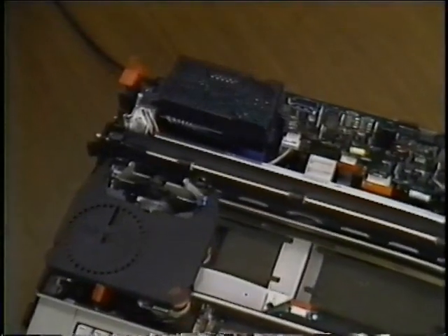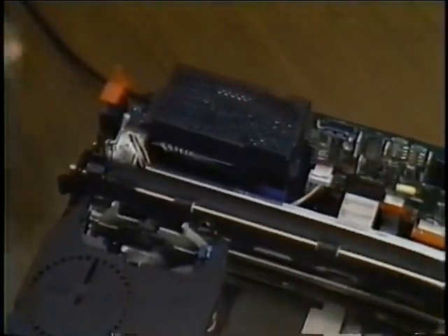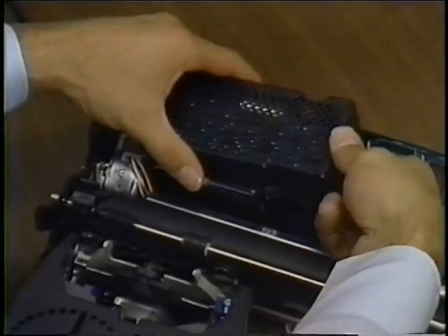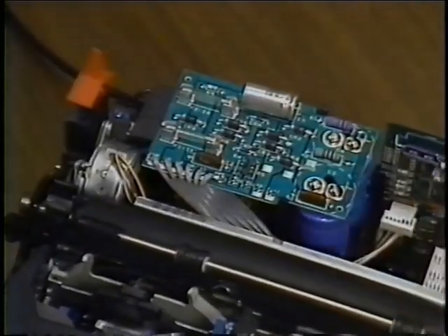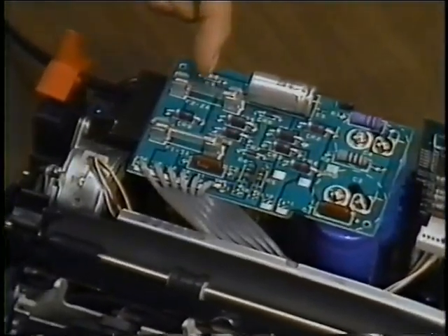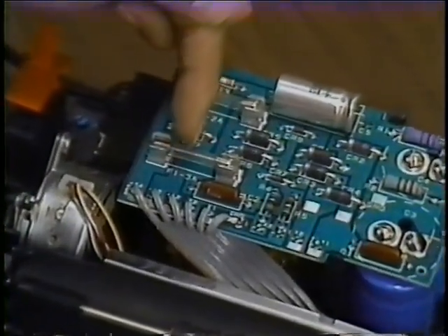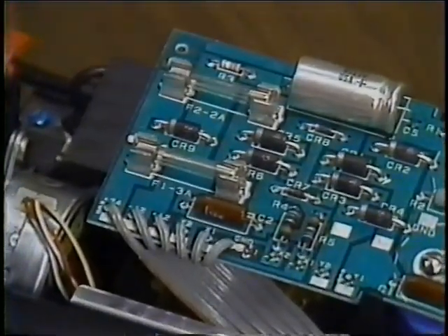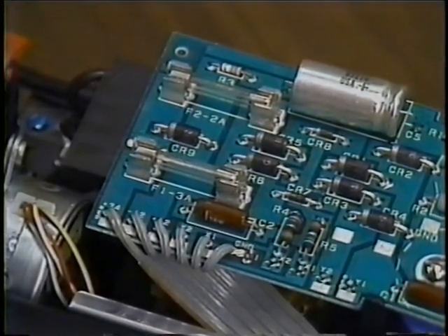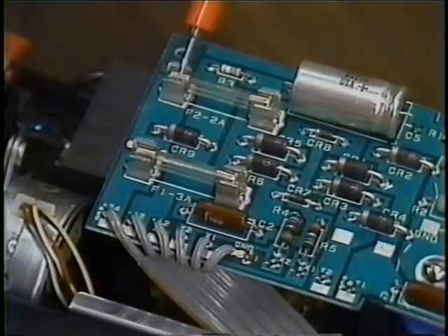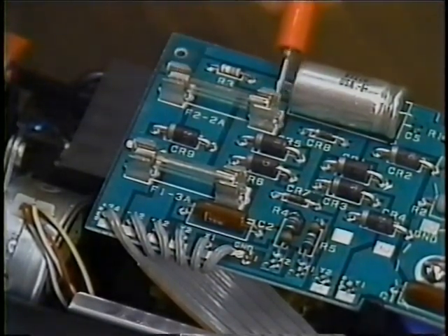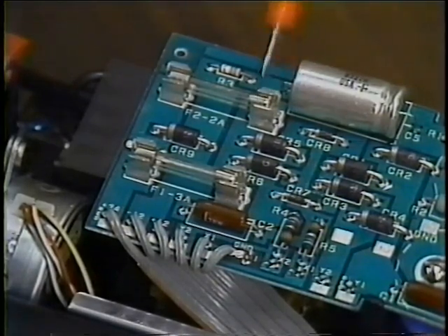There are 3 fuses in this machine. 2 of the fuses are on the rectifier board on the power supply. To get at these fuses, it is necessary to remove the power supply cover. To check a fuse, set your meter to measure 60 volts DC. Check for the same voltage on each side of the fuse.